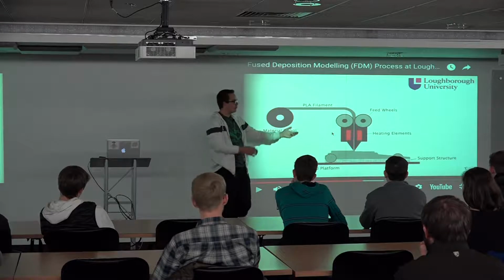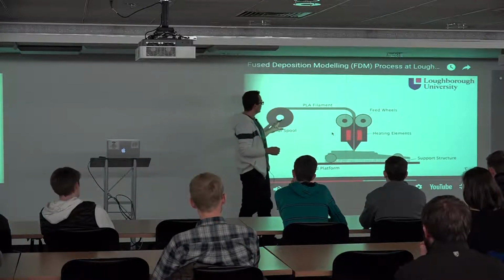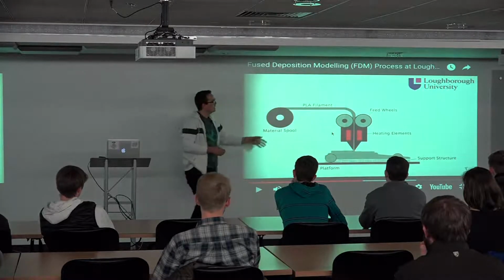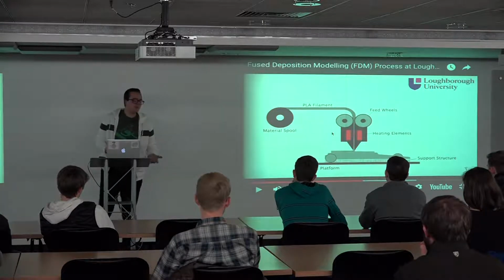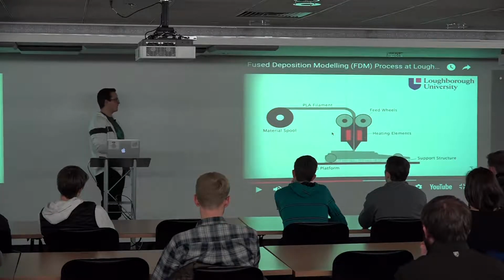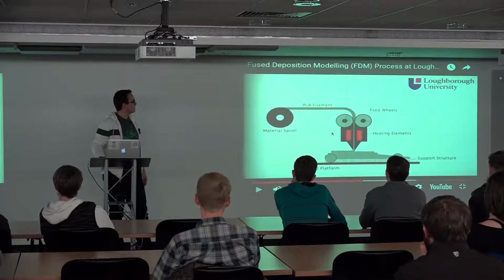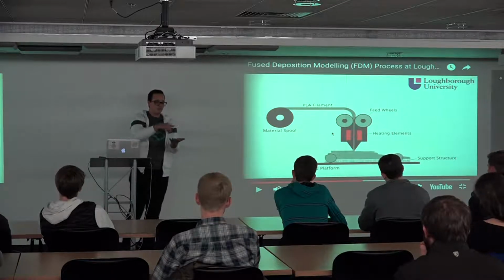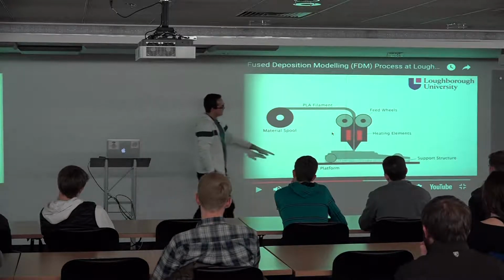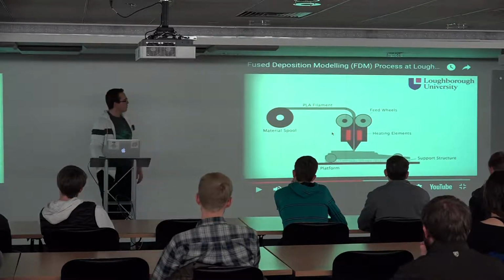You may have seen this kind of printing before. There are several different methods, and I think I have a slide on 2 of the more critical ones that we do. But this is just a simple extrusion 3D printing. I'll refer to it as FDM, or fused deposition modeling, which is a long term for spitting out plastic, kind of like a hot glue gun or any kind of extrusion process like that. But it basically extrudes material into a specific shape, and one layer at a time, it starts to build up the model. And that's the main type of 3D printing we have in our lab,